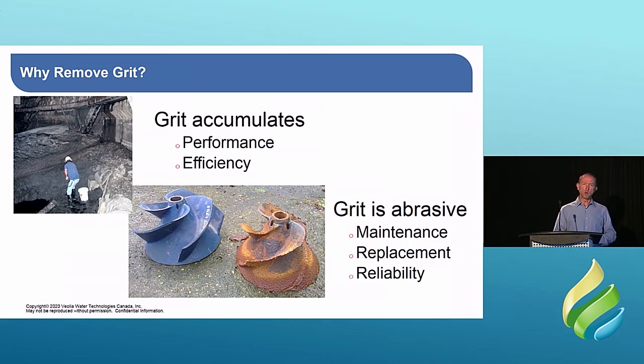Grit is also typically abrasive. Hard, inert material causes wear on things. So you're going to see premature failures, increased replacement frequencies, things failing in the middle of the night, don't they always? So those are really the reasons why you want to be thinking about removing grit.